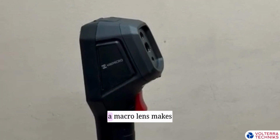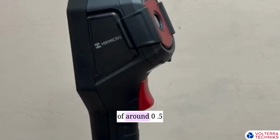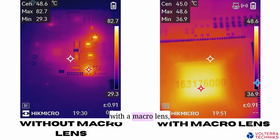Now, this is where a macro lens makes all the difference. Typically, most thermal cameras have a minimum focusing distance of around 0.5 to 1 meter, which makes capturing small PCB components clearly quite difficult. But with a macro lens, this distance is reduced to just a few centimeters, allowing you to get much closer and capture highly detailed thermal images of even the tiniest component.